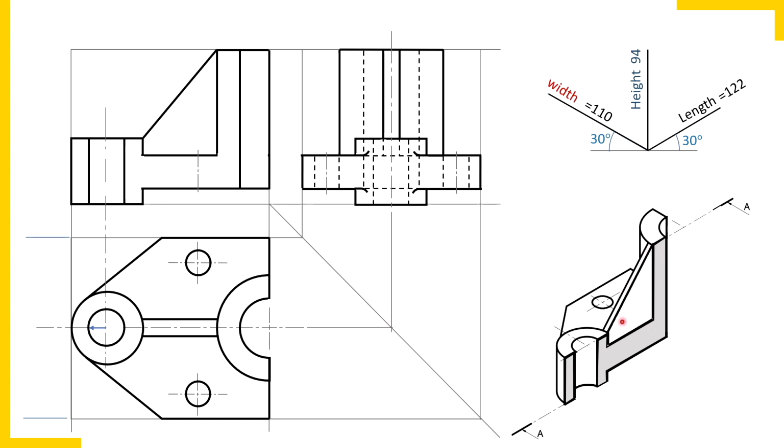So this trapezoidal surface now you are watching is the newly generated surface, and like this shaded surface in this pictorial view, focus on that red dot. Like this shaded surface, this trapezoidal surface is also newly generated surface, and it is in the same plane, that is plane of the cutting plane. So there must not be these edges indicating boundary of that trapezium. When two portions get cut by a cutting plane, boundary between the two shapes you should erase. Just say for example, cylinder and horizontal plate, boundary here we have erased in sectional orthographic.